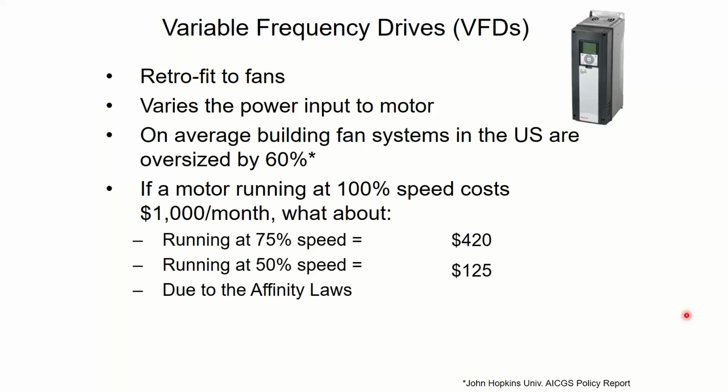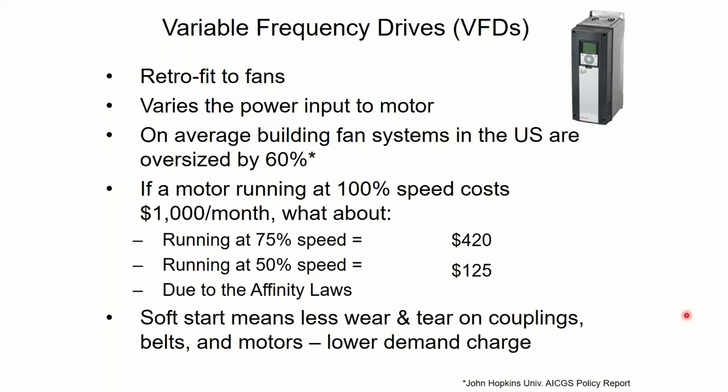$125. So if I cut all your fan speeds in half, I would cut all of your energy usage by an eighth, or almost an eighth. Actually, it is an eighth. It's a pretty substantial amount. This is due to something called the fan laws or the pump laws. Or if you work on fans and pumps both, then you play nice and you play Switzerland and you call it the affinity laws, which also sounds cool because it's a superhero kind of thing, right?